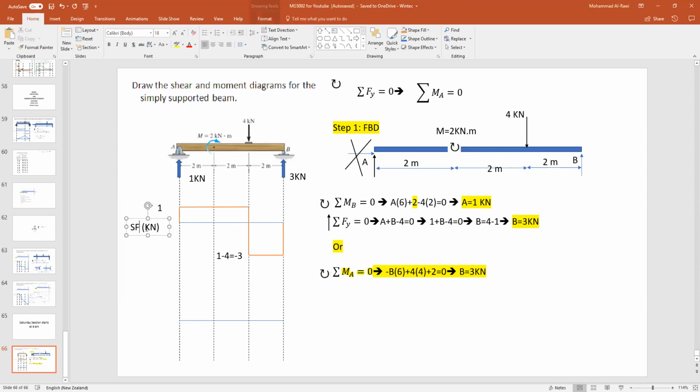Let's try to do the bending moment diagram and see how interesting it is, because I'm quite sure this is where the most common confusion about these kinds of questions lies. I just need to fix this. The bending moment diagram has units of kilonewtons times meters. And when I sketch the values, guys, I don't need to show the units. I just put numbers because I have already labeled the figure.